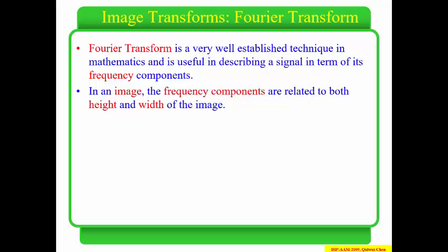The actual function, or let's say the function in the time domain, multiplied by a certain basis function. And this basis function is in the form of sine and cosine with different frequencies. So the idea is that I have my signal and I multiply it with sine and cosine functions having different frequencies, and I get the average of the result of this multiplication.